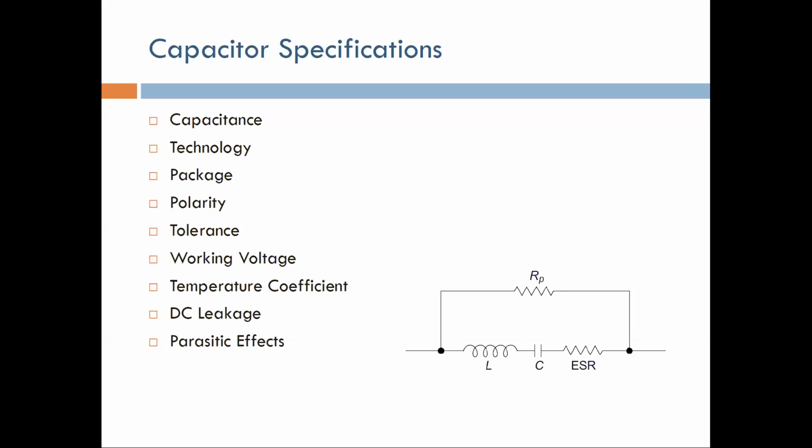If you charge a capacitor and leave it for a while, it's going to lose the voltage, even if you don't take any current from it, because the insulation, as we talked about before, is not a 100% insulator. It has very, very large resistance, but with time this very large resistance is going to pass enough current to discharge the capacitor. So you have a leakage resistance here.